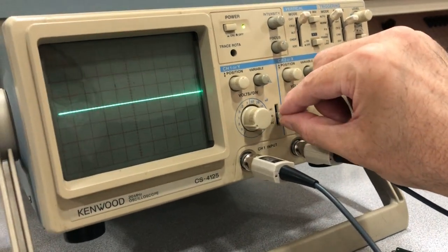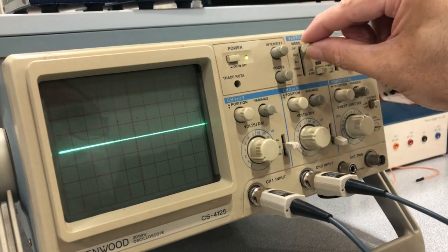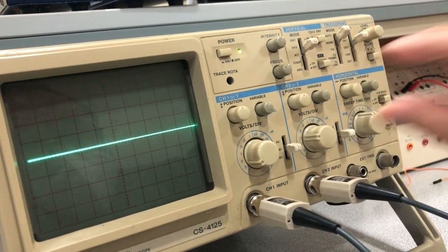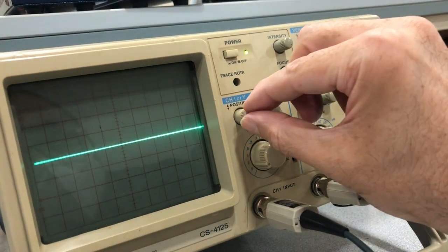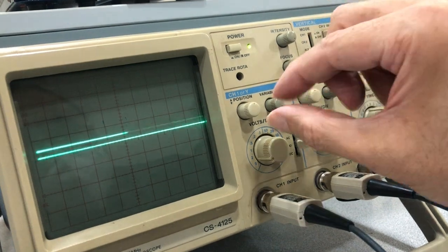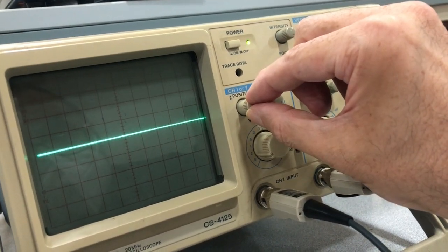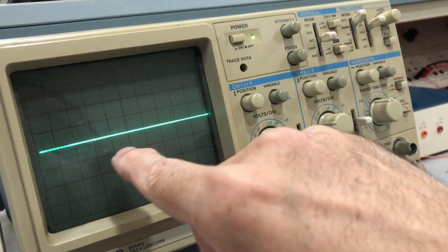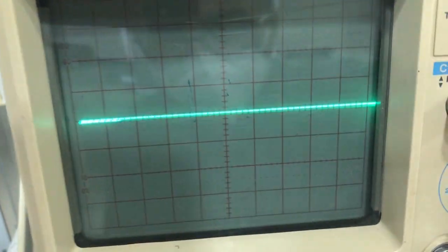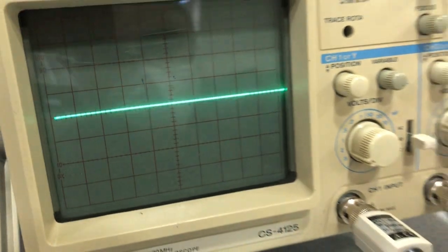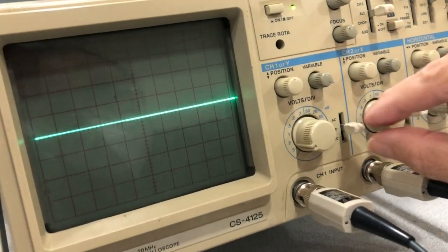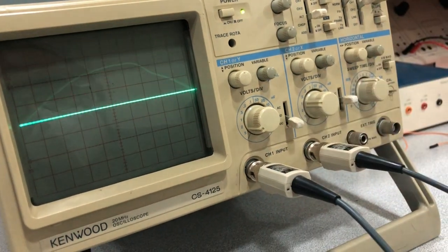Okay, but let me check my ground here and here. I have to turn on both of them, and I set them both to ground and verify my position. Now it's on alternating. This is my vertical position. They have to be superposed on top of each other on the time axes. And this is the position of channel 2, also on top of each other. And now the horizontal position, I take it to start exactly from the left. Now let me plot channel 1.